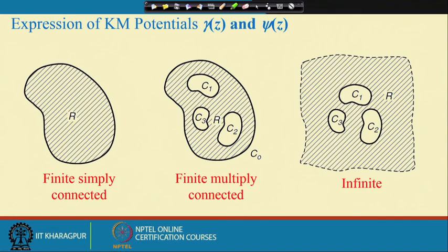But the only thing is, when we solved this purely in terms of x and y and phi, the Airy's stress function, it was just one function, the phi, that we had to choose. Now, in this case, the stress function is written in terms of two potentials. So, we have to assume two potentials. Now, you see, these assumptions are not very straightforward, unlike phi.